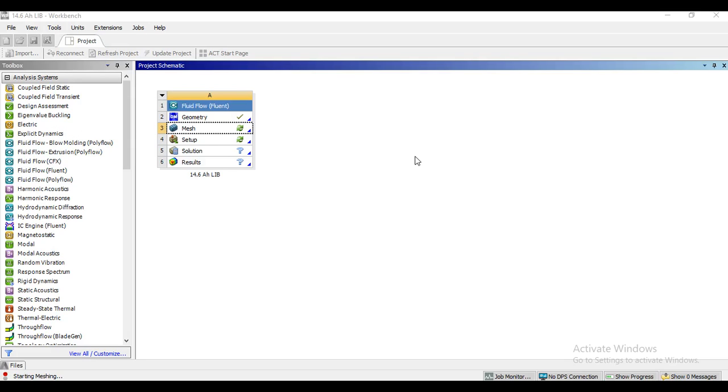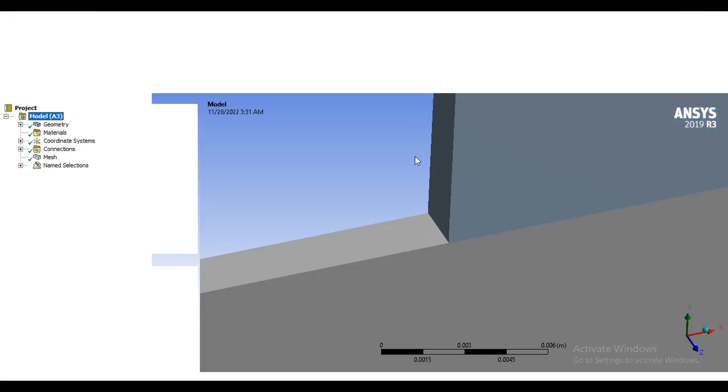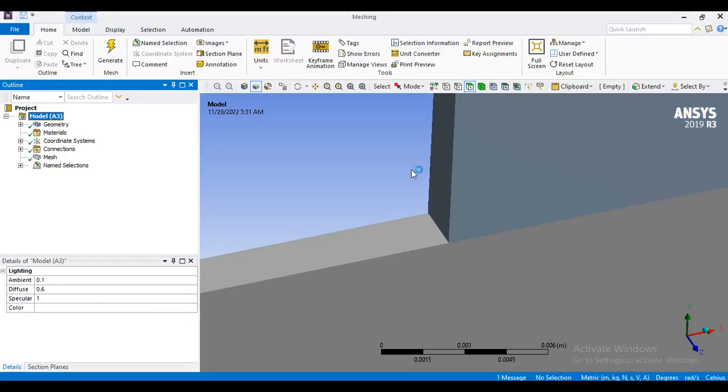As in this simulation, we're going to have a heat transfer from a solid to the liquid. We introduce an inflation for the mesh in order to capture the heat transfer accurately and see how the cooling is going to help the battery to keep it from thermal runaway.